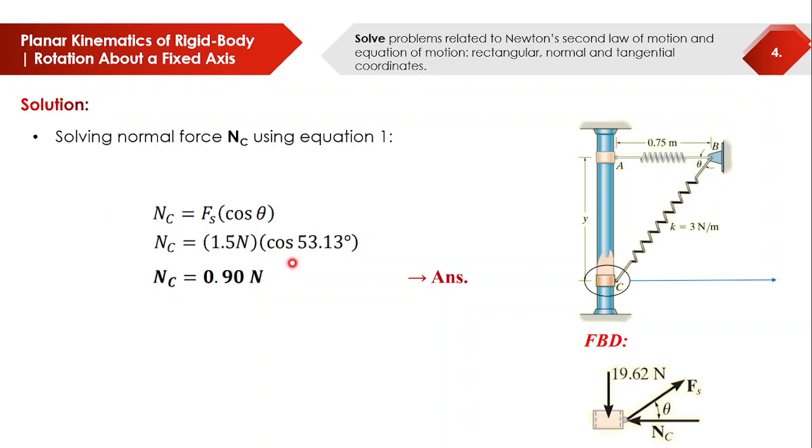So, more important, the highlight here is you should know how to solve for your spring force, no? That will be K times S. Then the free body diagram, since we already focused on this one. The idea in solving these kinds of problems is first you draw your FBD and then solve for the unknowns using the vertical component of the forces, and you can get equations from there.